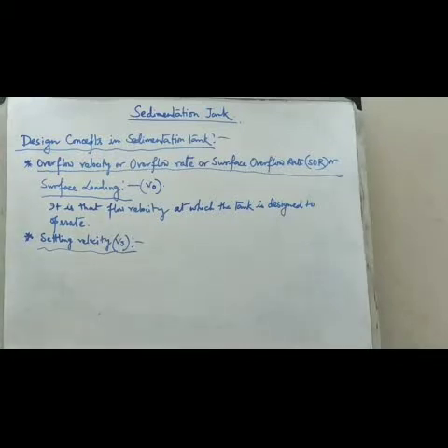The importance of these two terms can be understood easily by considering an upflow sedimentation tank. In this design, the particles fall downward and the water rises vertically upward. The rate at which the particle settles is the settling velocity, and the velocity of the liquid rising is the overflow rate.